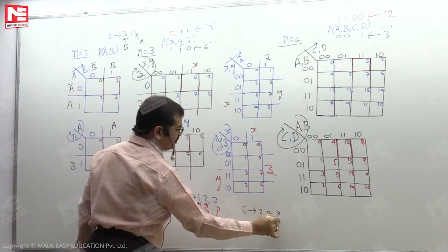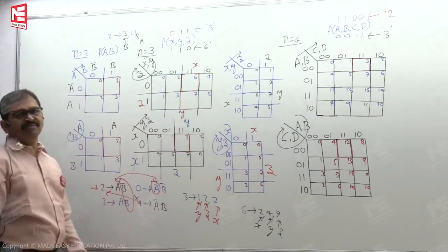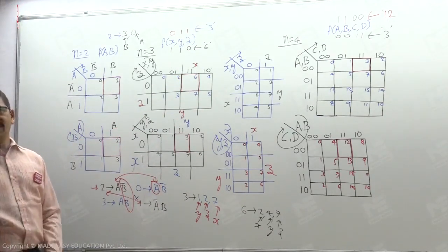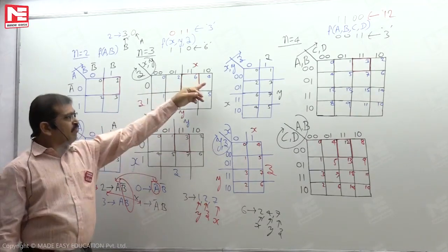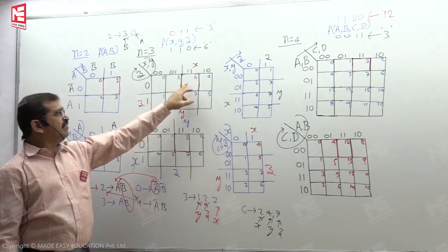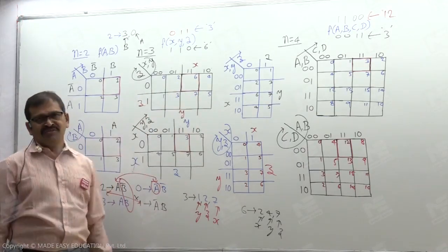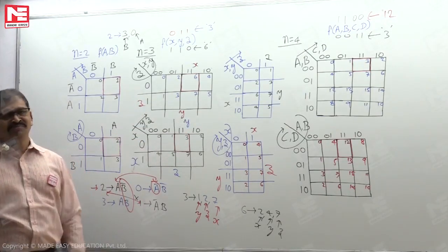It is an observation you can see. For cell 6 as the reference cell, 2, 4 and 7 are adjacent cells: 2 differs in variable x, 4 differs in variable y, 7 differs in variable z. Whether we read from any other format, it must be the same.